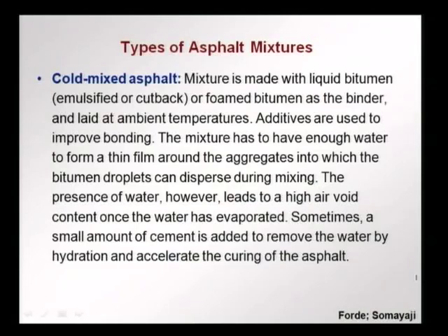Sometimes to remove this water faster and also to bind the water, instead of having it stay inside the asphalt, a small amount of cement is added which hydrates and combines with this water, thereby accelerating the curing of the asphalt itself and not having delays in the curing due to the presence of water. So, these are the different types of asphalt mixtures. The most common, as I mentioned earlier, is the hot mixed asphalt.